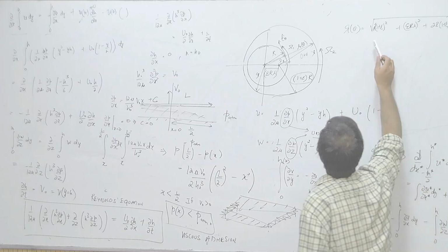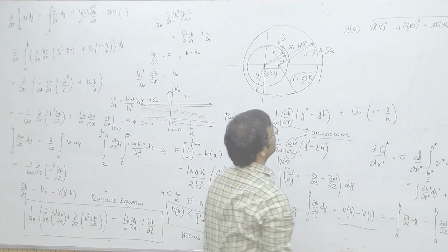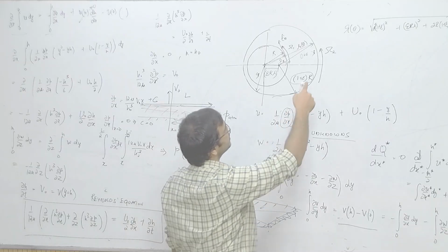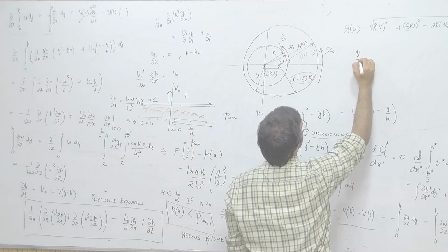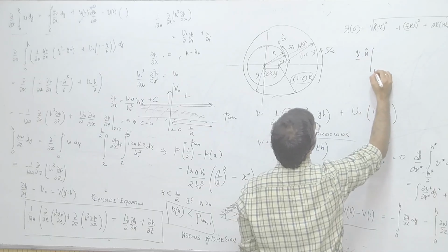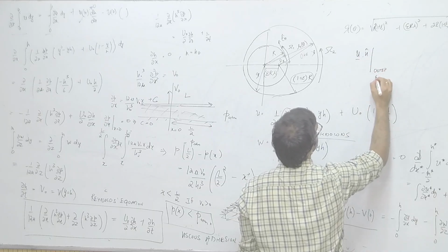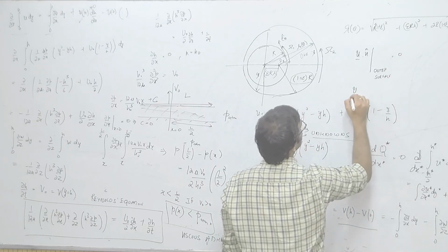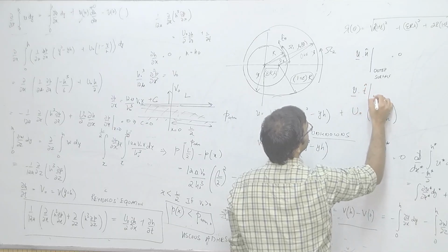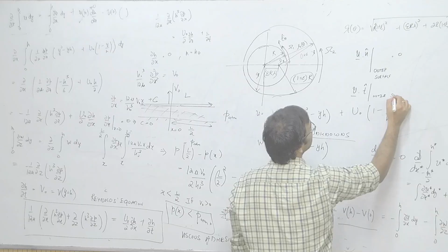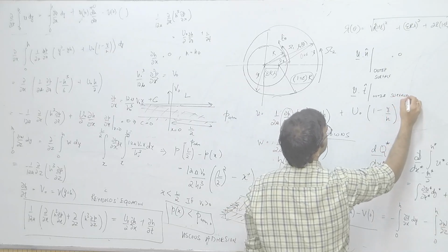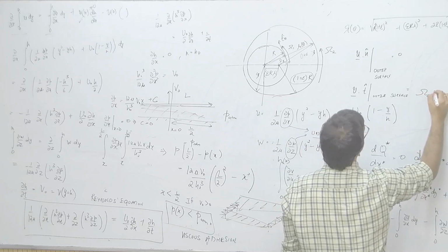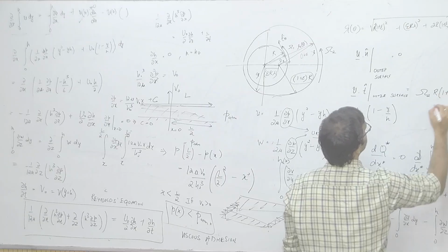So, you have to be careful when you apply the boundary conditions. In that case you will have that u dot n at the outer cylinder surface will be 0, and u dot t again at the outer surface, where this t is the tangential unit vector, will be equal to omega 2 times r 1 plus epsilon.